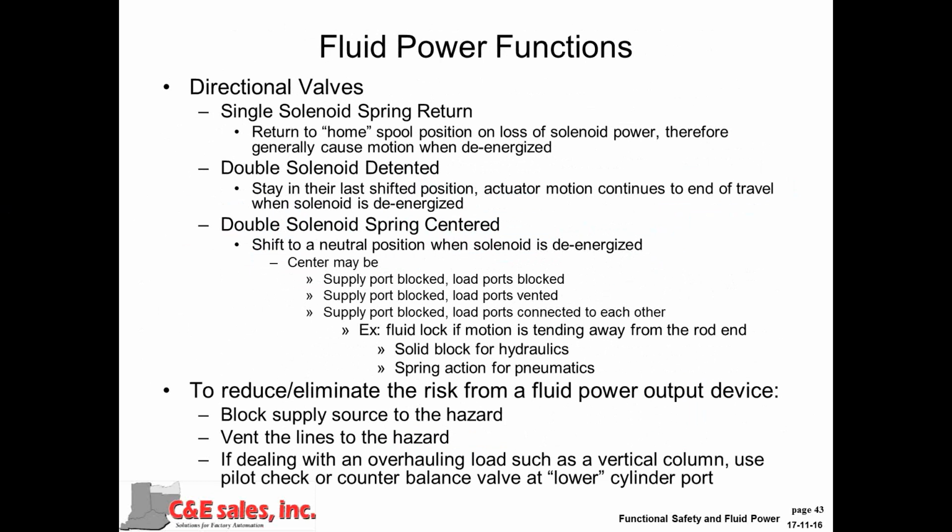A little bit on fluid power. Fluid power are a lot different devices because they have certain unique responses that are a function of the device itself. We have the single solenoid spring return, which is a device where when we remove power from the solenoid, the spool shifts back, which means that there is a high possibility that when we drop the solenoid power, it might initiate a motion. If, for example, the cylinder had been advanced, it would return when we lose that power.